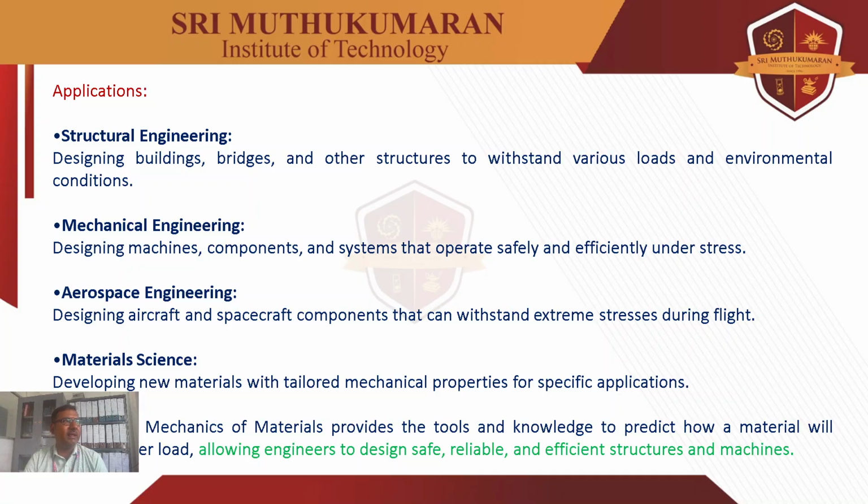What are the new materials nowadays? Iron is heavy, and it is being replaced by hybrid composites. A hybrid composite combines natural composite and synthetic composite. Synthetic composites use glass, carbon, and Kevlar fibers. Natural fibers are mostly jute fiber and banana fiber, and natural fibers are applicable for natural composites. These are replacing iron because of their low weight and high strength ratio. This is about developing new material properties.